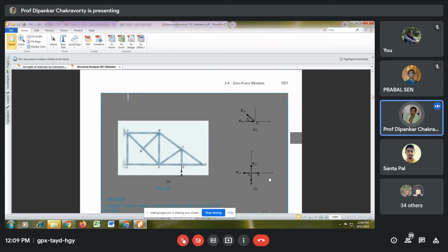Or in other words, if three members form an equilibrium, or four members, whatever, then a closed polygon has to be formed. If you have three arrows where two arrows are in the same line, can you form a closed triangle? No, you can't. But in H, if you have a particular force, then AH and FH are in the same line. I agree. But then HD and the force can assume reasonable magnitudes to form a vector quadrilateral, although two lines are the same line.